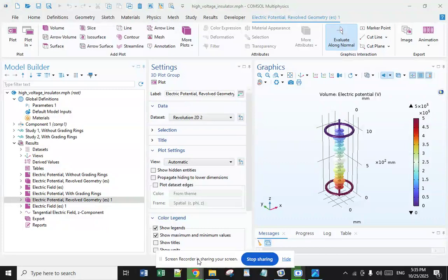And what about the environmental conditions? Environmental conditions play a crucial role in the performance of insulators. Contamination, whether in the form of dust, sea salt, or industrial waste, can deposit on the surface of insulators, reducing their effectiveness, and moisture combined with contamination can lead to the formation of a conductive layer on the insulator, increasing the risk of surface electrical discharge. In addition, extreme temperatures and exposure to ultraviolet radiation can affect the integrity of the material over time.